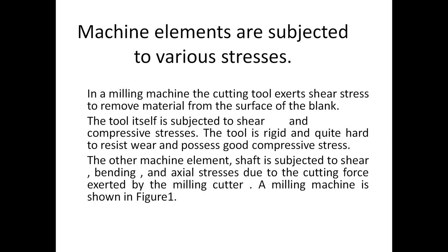Therefore, shearing of the shaft may take place because of the induced shear stress. When the induced shear stress exceeds the permissible limit or the maximum shear strength of the material with which the shaft is made, failure takes place. Therefore, it is essential to design the shaft safely, otherwise failure may take place.